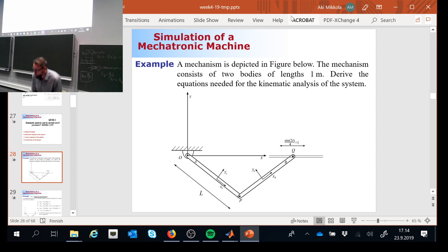All right, so we're going to follow that. With the help of that equation, we're going to be able to express the Jacobian matrix that we need in order to compute the Newton difference. And once we have the Newton difference, then we can solve the position level analysis, or we could go to the velocity level, and then acceleration finally. So let's take a look.